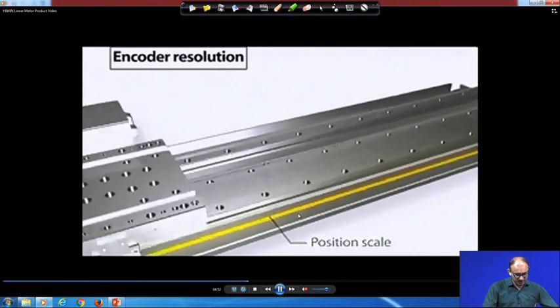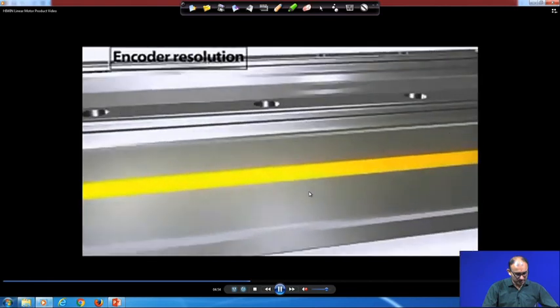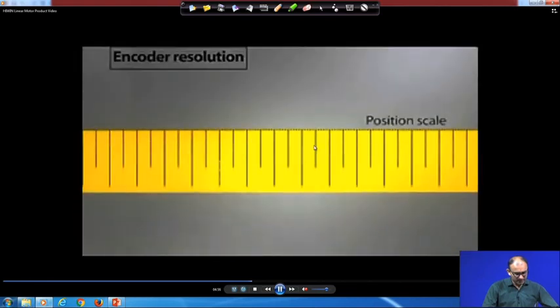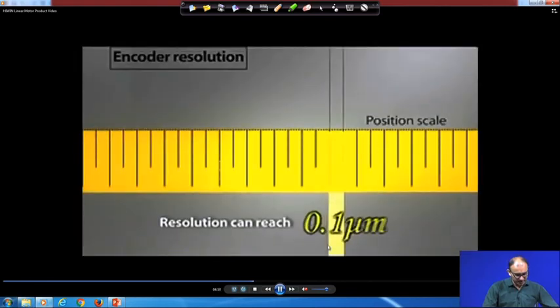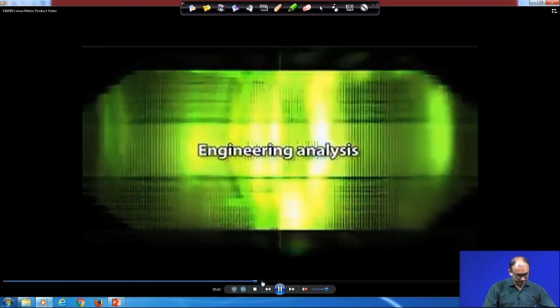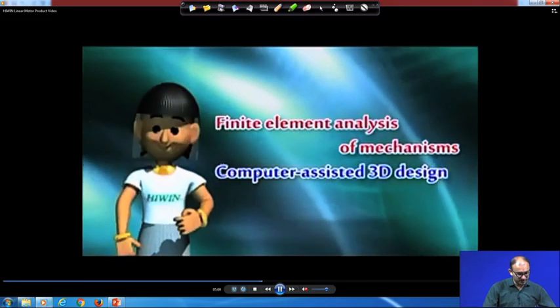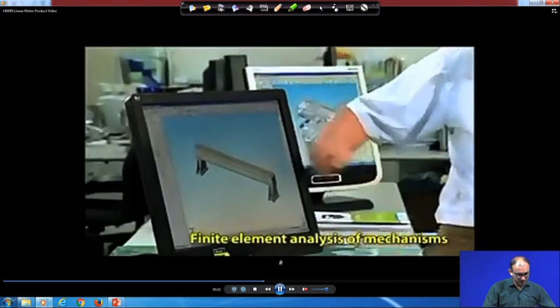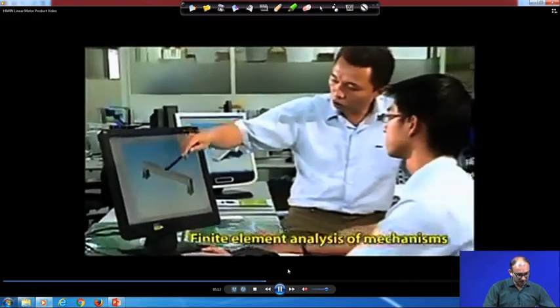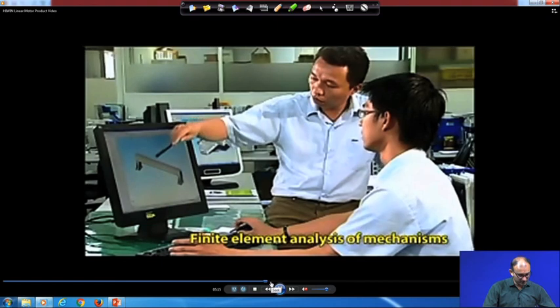Right. So, this is the position scale attached here. There are different markings, called the position scale, and each one you can get with 0.1 micron. And then when you build this system, you have to supply the current, and you have to finalize the straightness, the losses of the current under operation, and the heating of the system.